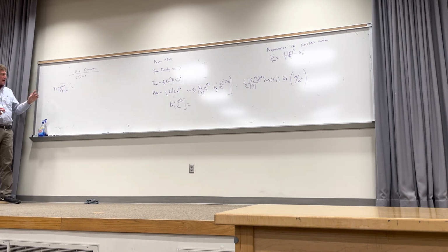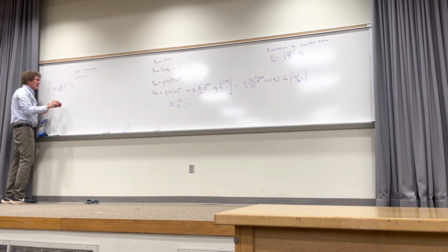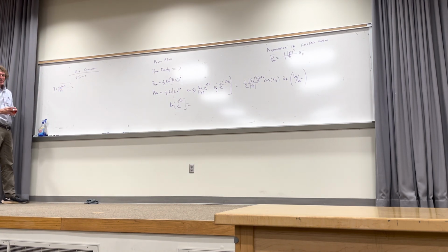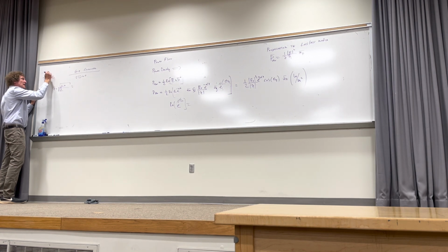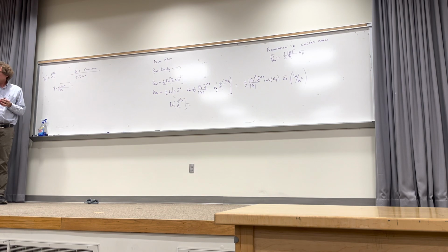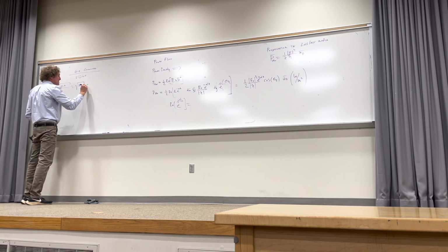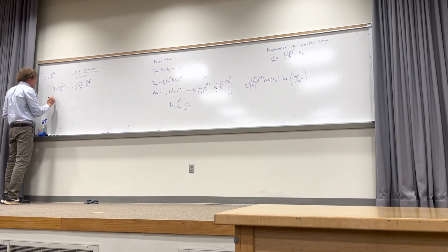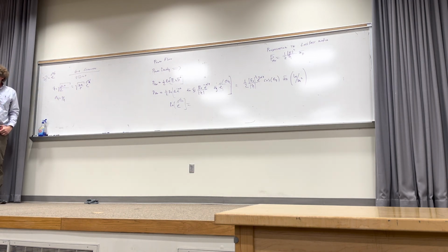Now, if it's a good conductor, how do I reduce the complexity? Yeah, the j omega epsilon goes away, right? Y'all follow me? Now I have this. Well, square root of j is really what? It's e to the j pi over 4, or 45 degrees, isn't it, class? So I can say this is really equal to the square root of omega mu over sigma, and then I have e to the j pi over 4. That means the angle associated with eta is simply pi over 4. I got a magnitude and an angle, correct? Times e to the j angle.